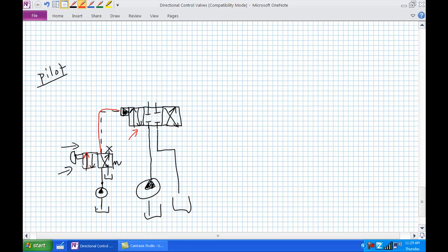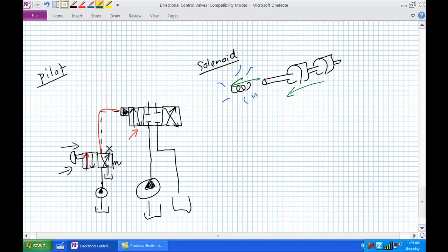Okay, so solenoids, like I said earlier, have our spool connected all together, and a little electromagnet, when energized, pulls the spool into it, and accordingly everything else comes with it and changes direction, stops, starts, or changes direction of fluid flow. What's the advantage here? What's cool is basically they're efficient and quick acting. Electrical signal, snap, boom, it moves.